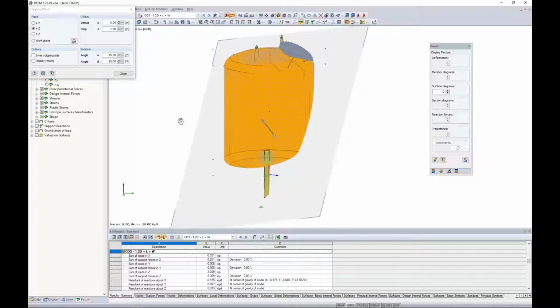So obviously the clipping plane may be an advantage to use when we're looking at these enclosed type structures such as tank elements. Where it's an even bigger advantage, as you can imagine, would be with 3D solid elements. So where we truly can't visualize the stresses on the interior of the solid element, well, clipping planes can become very useful.